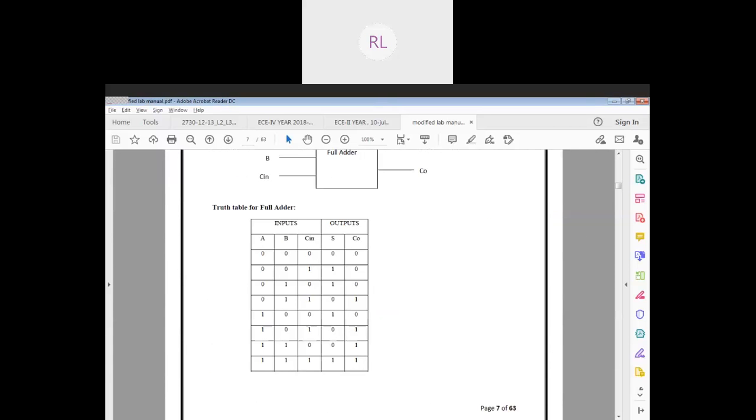And let us see the last case here, where you have 1 plus 1 is actually 0, and then 0 plus 1 gives me 1. Because of this 1 and 1, 1 plus 1, I am actually getting a carry, which is 1, the same that we saw previously for your half adder. You have 1 plus 1, sum is 0, carry is 1. So to this 0, again I am adding 1, so I get 1, 1. So I'm getting 1 and 1 here. I hope you have understood this truth table, right?